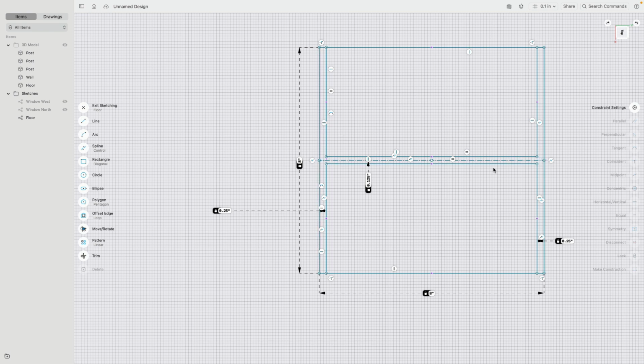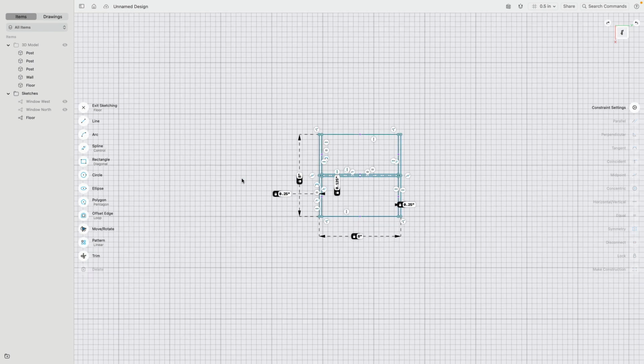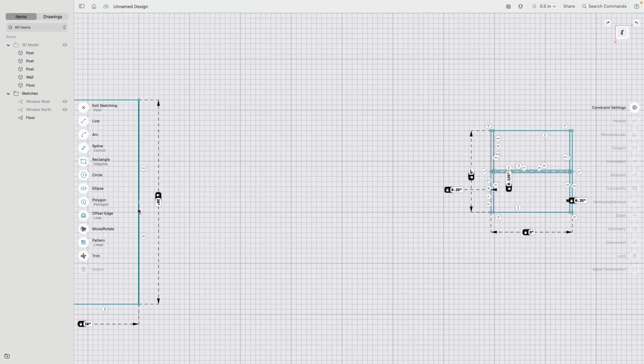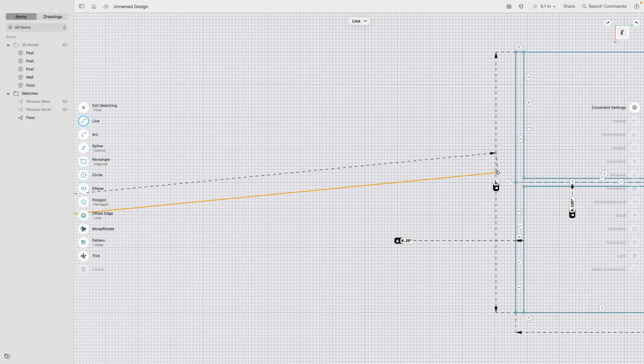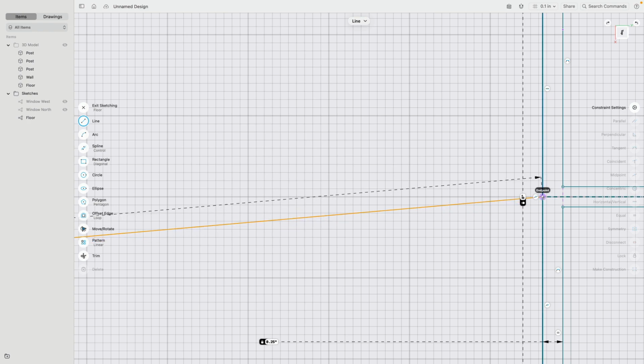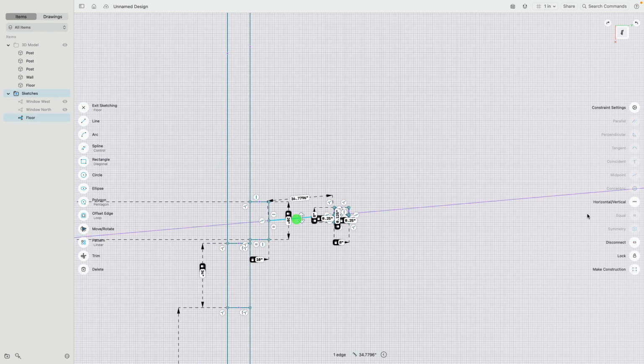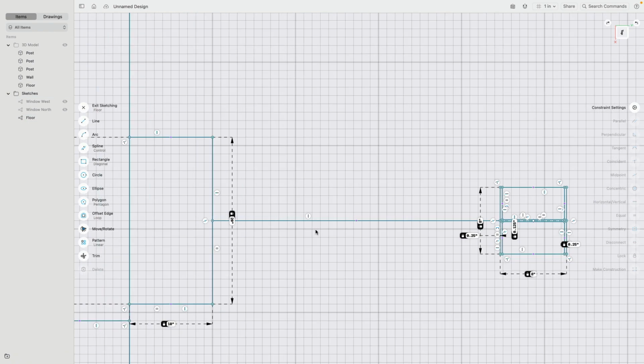You see now we have this H in it. Okay. How do we position this now correctly? You see nicely every line has a mid and then start endpoint. So I can draw from this midpoint to there a point. Press escape, escape. Then this line I make horizontal. That pulls it down. Now this is perfectly aligned.